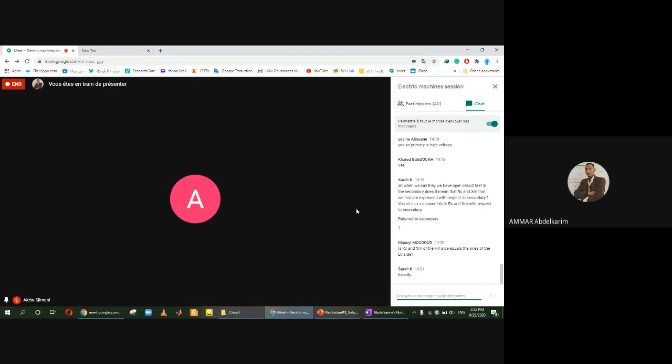So it's our choice. Concerning RC and XM, they are in the primary. Why are they in the primary? We have seen that apart from the current of the primary, it flows through the core, the parallel branch. So RC and XM are in the primary.